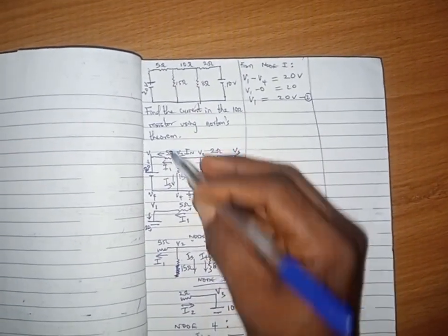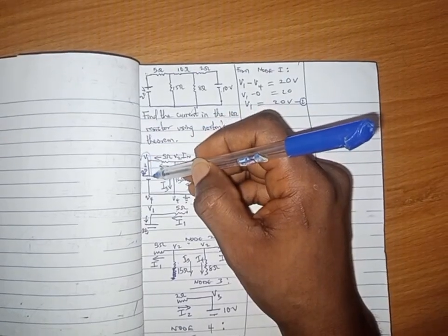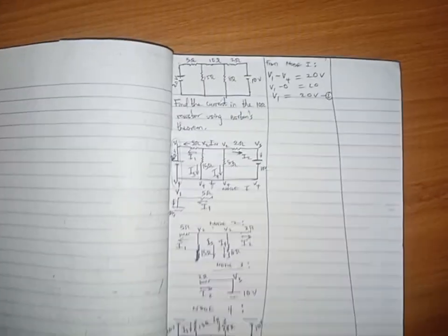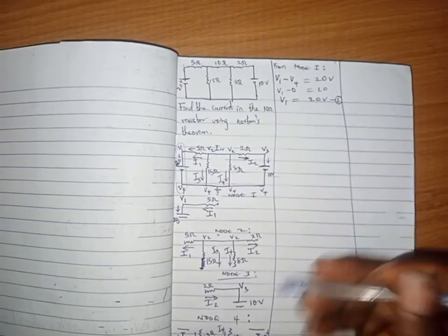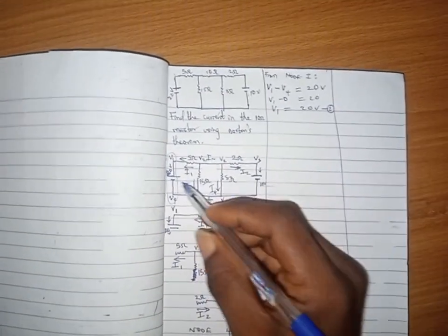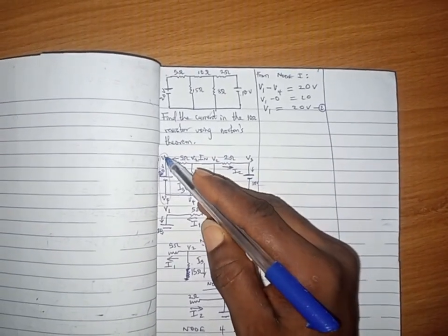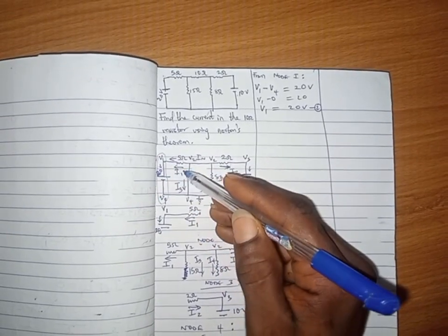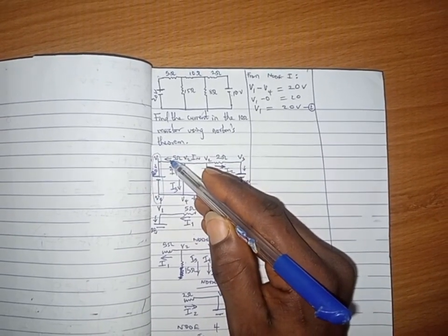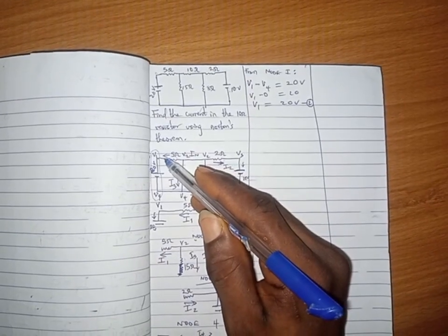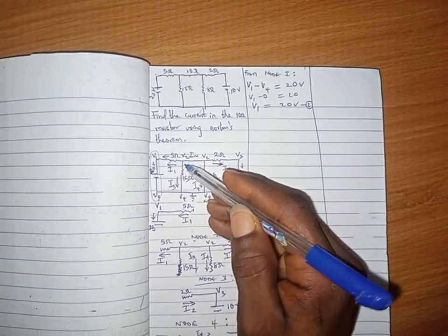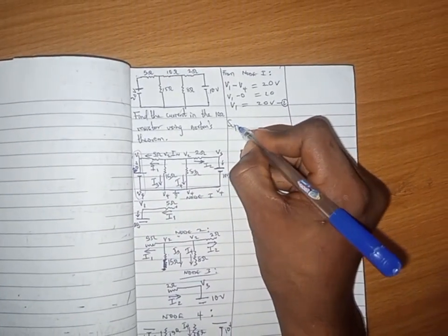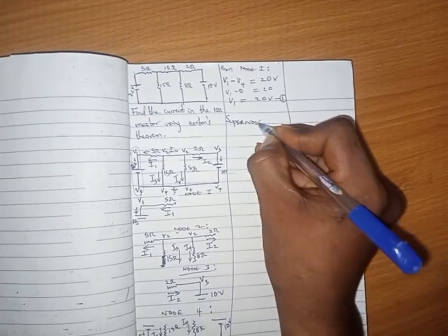Now that I've gotten that, I told you that anytime you do this, upper voltage minus, or higher voltage minus lower voltage, equals middle voltage, always find the super node immediately. And super node is simply if you overlook all the voltages there, both the up, the down, the middle: what currents are entering the upper voltage and leaving the upper voltage, and what currents do you have entering the lower voltage and leaving the lower voltage. So let's say super node equation 1. So super node 1.